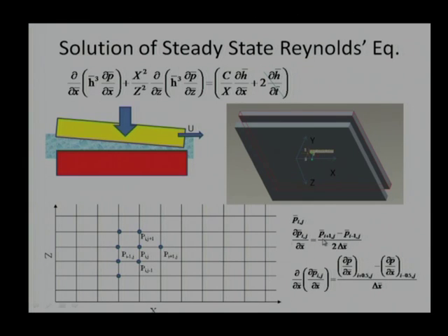We are averaging to find the gradient at p i j. We are taking help of one advanced node in the x direction and one node which is lesser by 1 unit compared to p i j. That is why p i plus 1 j and p i minus 1 j. If I know the neighbor nodes' values, I can get the results.